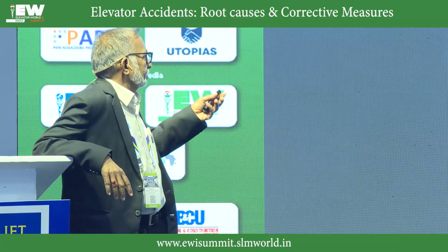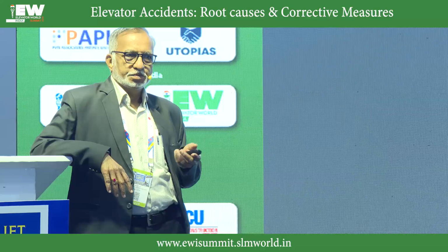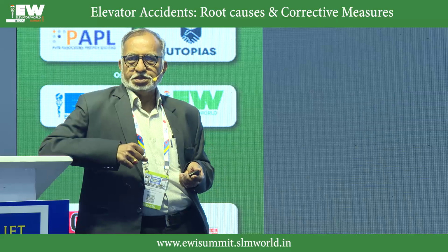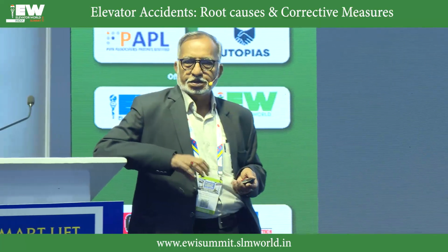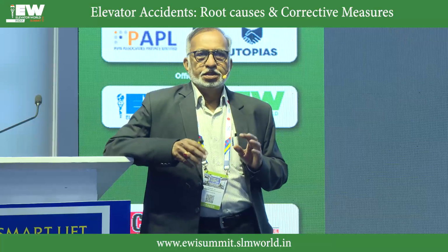Say fire people or maybe some technicians are trying to open the doors. The right way is to switch off the machine, control supply, then open the brakes and then take the elevator to the floor and then take out the passengers. The fire people generally do all these things only. Whenever they are called in a trapped situation, their first priority is to take out the trapped passenger. And in that case, they break open the door and then try to remove them.